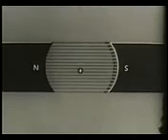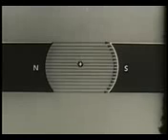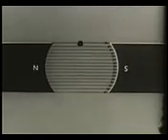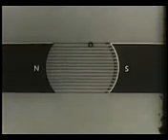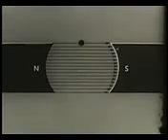But the conductor in an actual machine is not moving in a straight line, but rotating. When the conductor moves in a rotary path, the number of lines cut varies depending on the position of the conductor. At the top of the field, for instance, no lines are being cut and no EMF is generated.